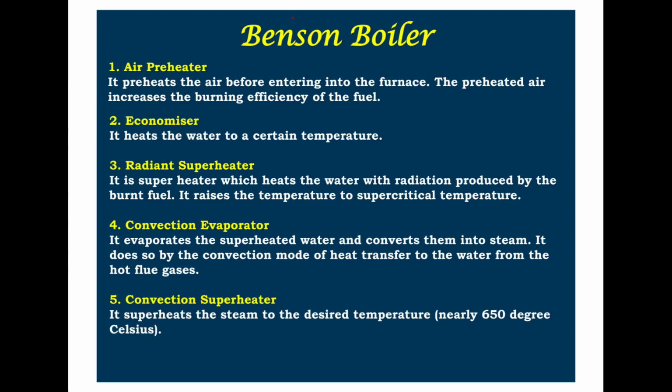These are all the Benson boiler mountings. The first one is the air preheater. It preheats the air before it enters the furnace. The preheated air increases the burning efficiency of the fuel like coal.